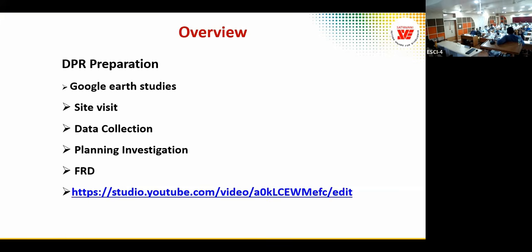But drafting the requirement of the topographic survey is a very, very important part, because this covers everything, the variation in the project site condition. You must have seen in many projects, why is there variation in the site condition? What is the variation between survey and project implementation? That means you have not done the survey properly. If there is a variation, it means the survey is incomplete or inadequate.